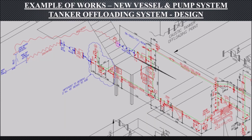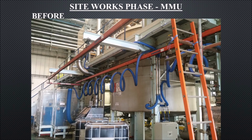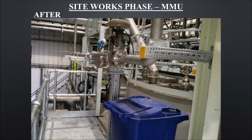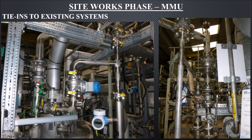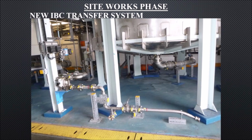The tank farm work was completed when the tank offloading system was installed. The new system had to be routed into existing vessels, requiring platform extension for access. Here's a photo before the works. Once a platform is installed, the new pipe runs and inline equipment are in accessible locations, with tie-ins to existing. An additional chemical had to be dosed into the makeup vessels, requiring the assessment and recertification of an existing vessel for use with a new pumping system, including transfer from IBCs.